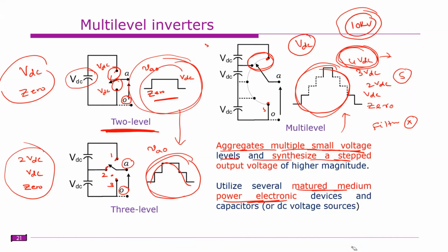Why are we going for a multi-level inverter? If that is the question, it is to increase the power levels. Either we can directly increase the power levels or increase the voltage handling of the inverter. So to increase the voltage handling and the power levels of the inverters, we are using multi-level inverters.